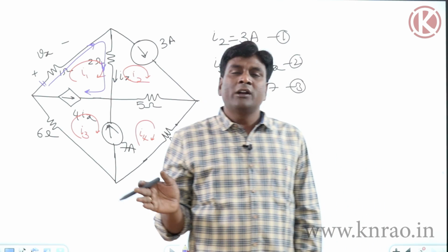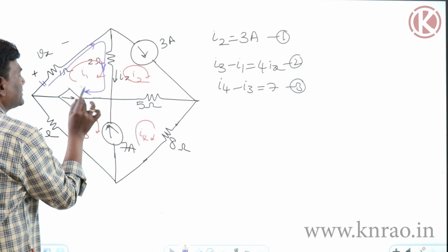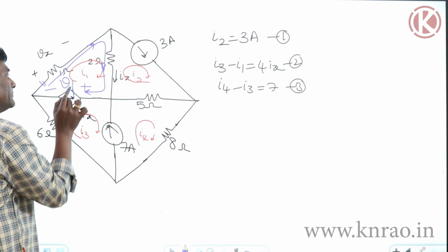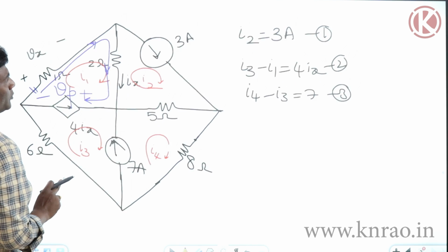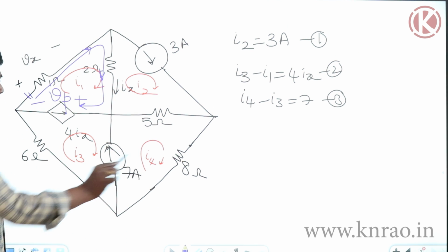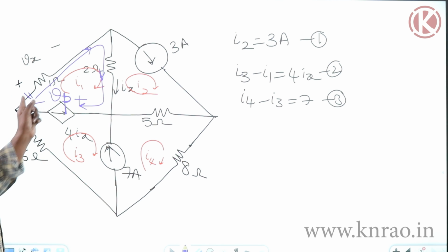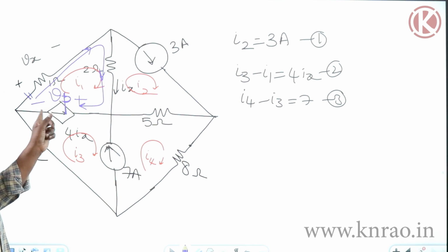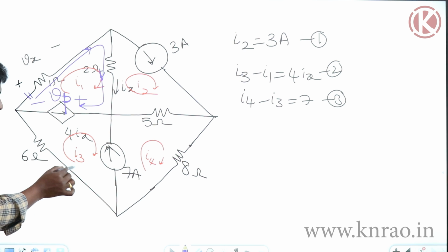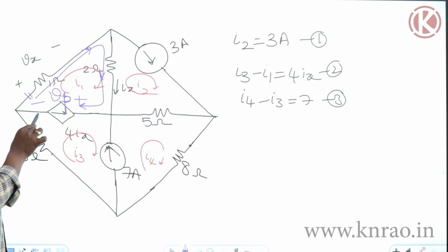Actually, in our nodal analysis, what I have taken is Ix. For example, if I take the voltage across this as Vp, hope you are able to see now. Now if you apply KVL, this voltage you will be able to write, this voltage you will be able to write, but this voltage you don't know, that's why you write it in terms of Vp. While applying KVL here, plus Vp will come, and there minus Vp will come, so combinedly only one equation will come.